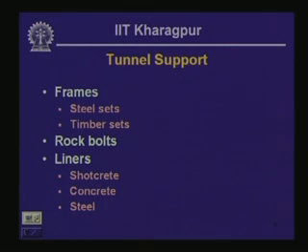They include shotcrete, concrete or steel liners, which are all in close contact along the entire surface of the tunnel wall with the surrounding rock, and because of this contact they provide stability to the possible unstable rock mass near the wall and the roof of the tunnel.